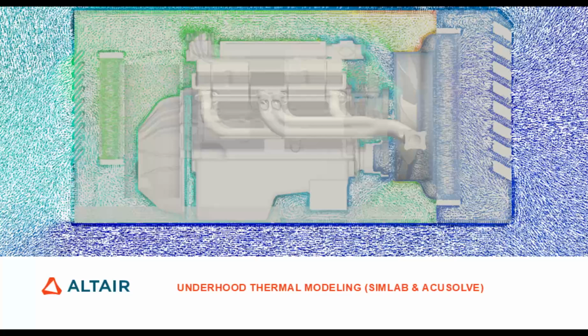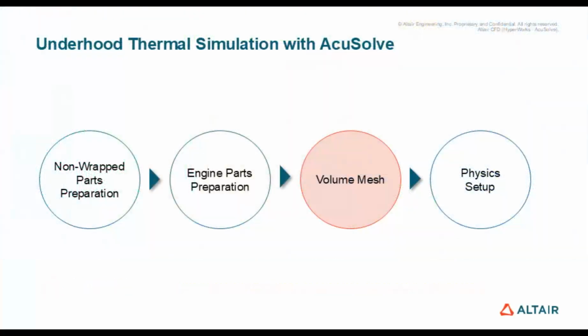Hello everyone, welcome back to the e-learning modules for Underhood thermal application using SimLab as the preprocessor and AcuSolve as the solver. This is the third video of the series. We will connect two surface mesh bodies together, place the volume mesh controls, and CFD mesh the model.